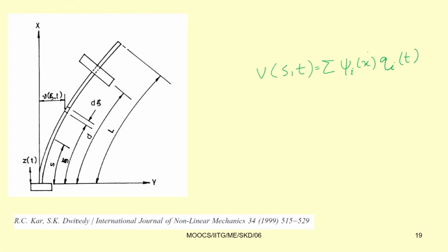So, it is a function of both space and time, unlike in a lumped parameter system where the displacement is a function of time only. Last class we first derived the spatio-temporal equation of motion using the D'Alembert principle, where we took M_s equal to EI times kappa_s, and kappa_s equal to phi dash, where phi is the angle.